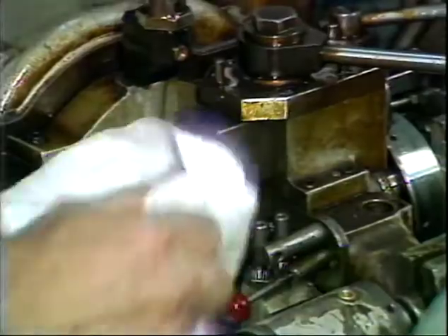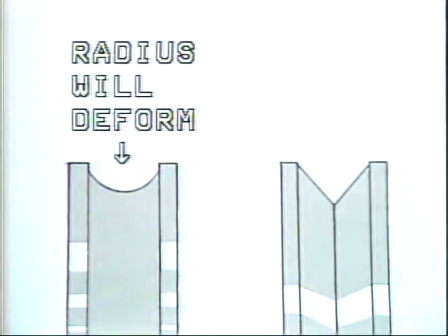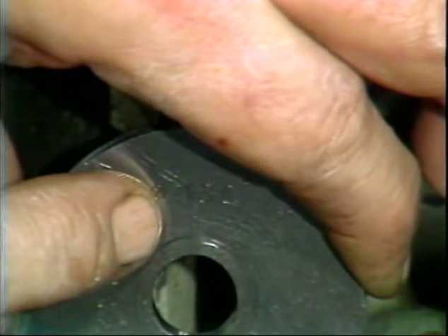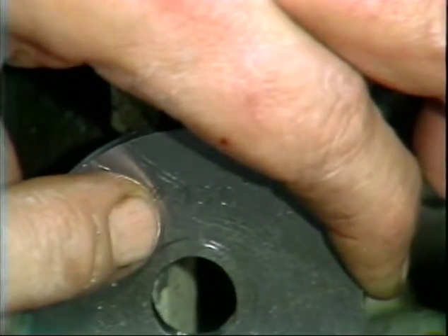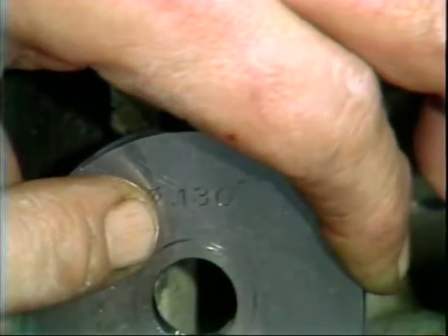Wipe off the feed roll shafts and mounting area. Inspect your feed rolls for excessive wear. The groove surface may be worn and will not properly feed stock. Mount the lower feed roll onto the feed roll shaft. Make sure that the feed roll size markings face out toward the operator's side of the machine.